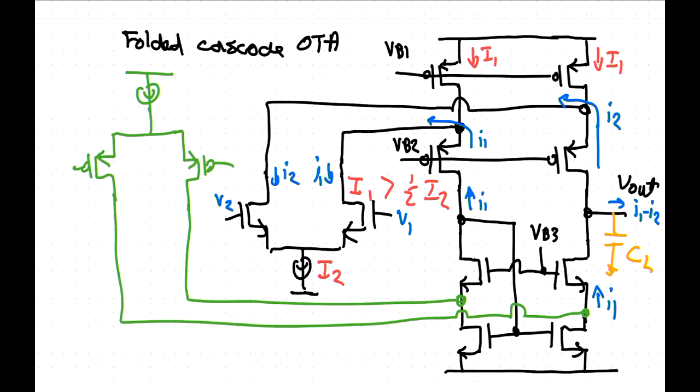On the other hand, if we put in a current here, that's going to take away from the current that goes in here. So pushing in current here is going to go this way, whereas putting in current here is going to go that way. So this looks like you can subtract the two currents on these nodes here rather than doing it up here. Which is funny, but very useful.